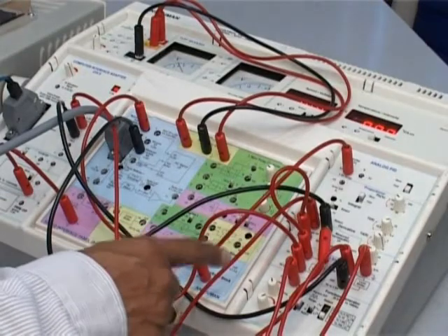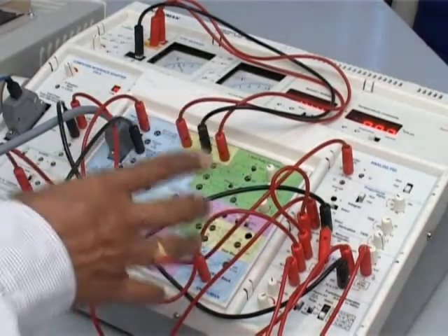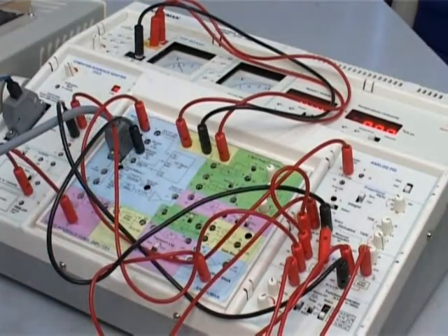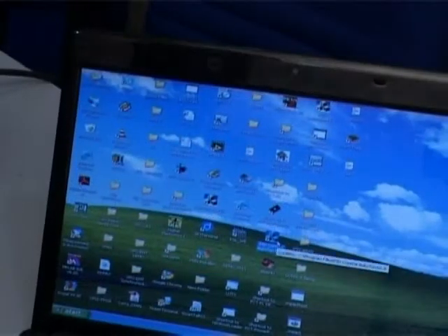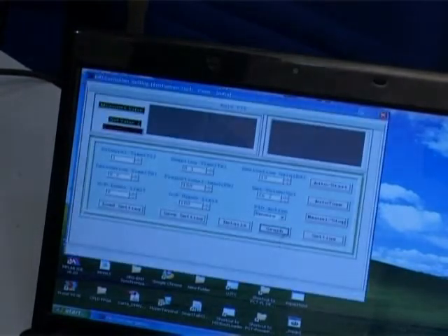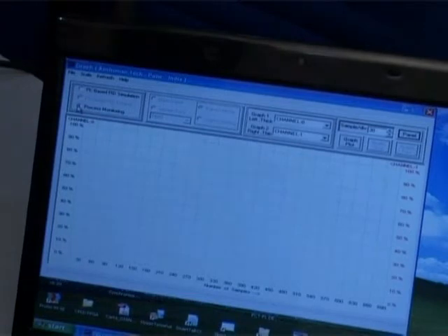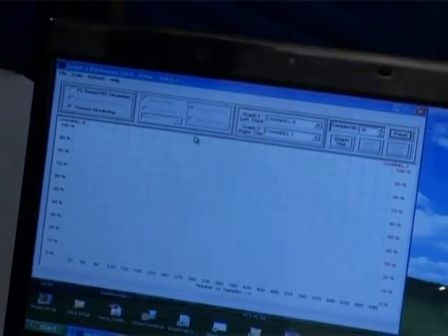Here, according to your function generator input, the motor will rotate. Go to PID 10, click at PID 10.9, graph. Here you go to process monitor mode because you are doing the experiment using analog PID.